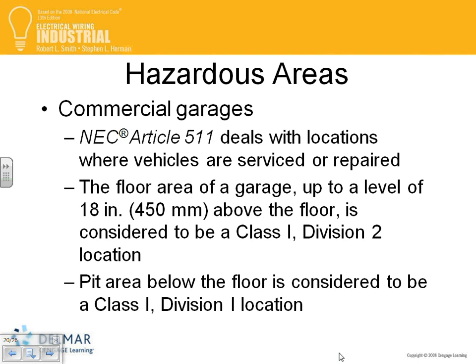Commercial garage. You have a commercial garage, guys, outside. You want to work a commercial garage. Very important. We encounter this all the time. A commercial garage is a hazardous location. Anything up to 18 inches is a Class 1 Div 2.